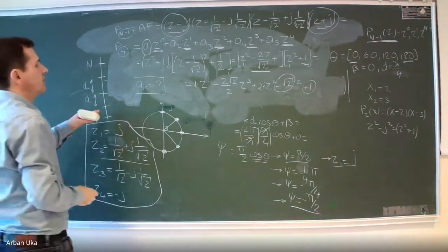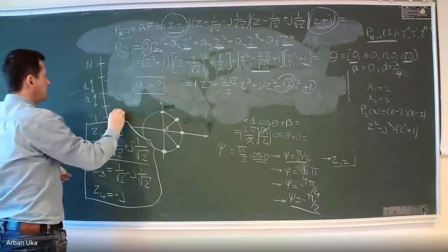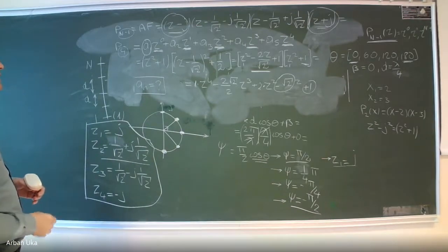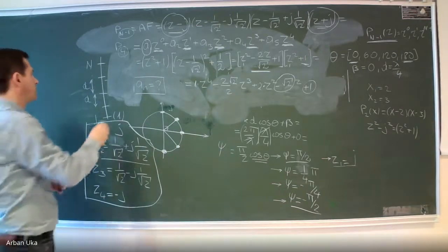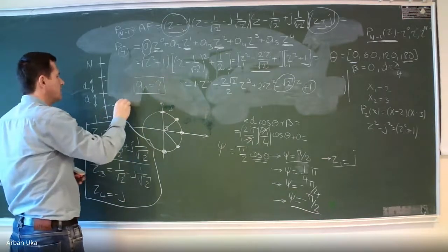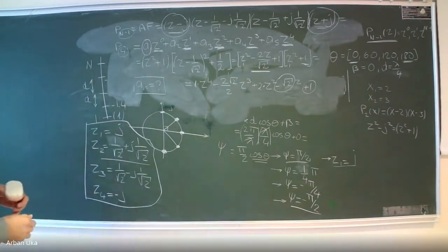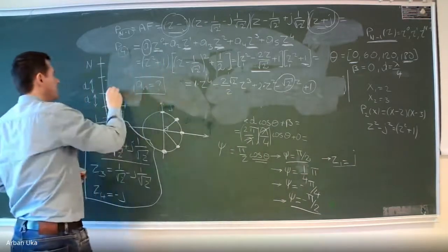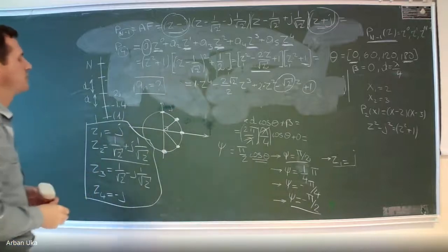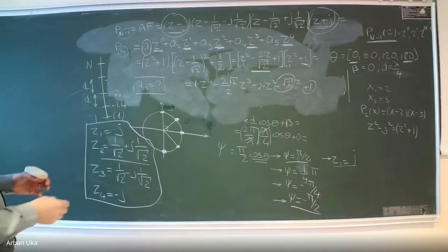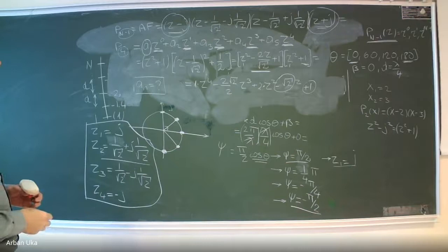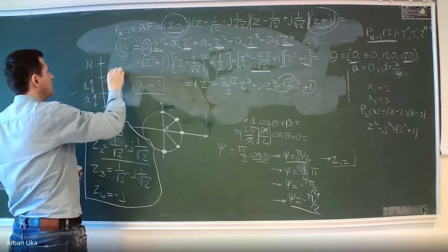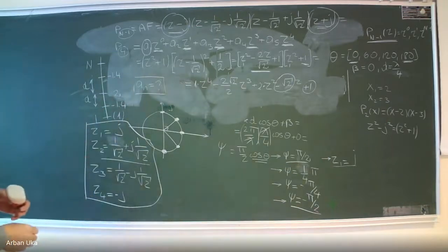Let's write them here. So A1 will have an excitation factor of 1. Then the next component is minus 1.4. The third component is 2. So actually, it's reading these backwards. So here the excitation coefficient is 2. Then the next one is minus square root of 2, so it's minus 1.4. And then we get 1.